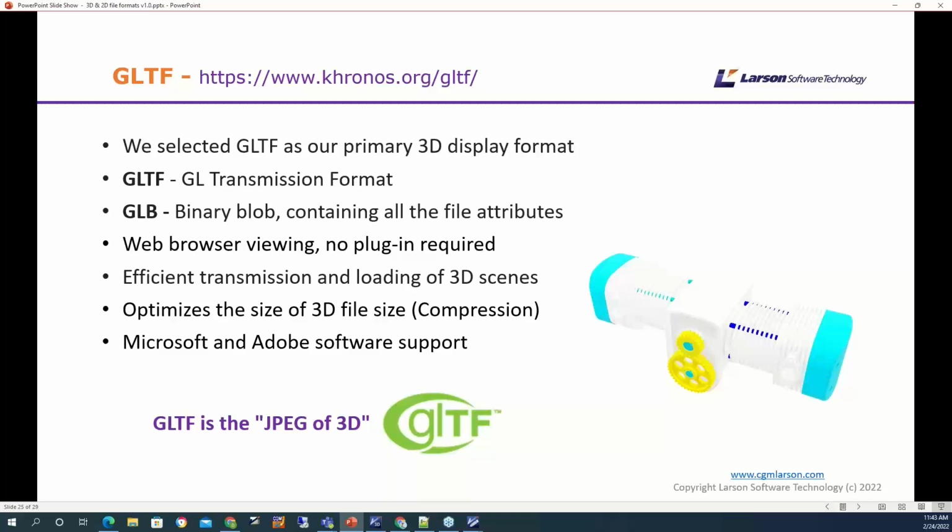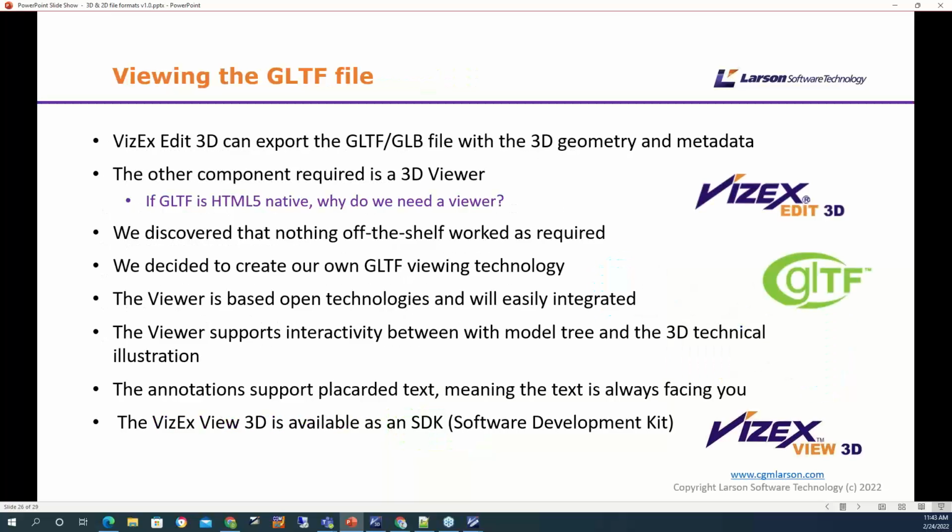So that should give us really good interoperability with other software. We can export as a GLTF, or GLB, it's the same file but a binary file. GLTF tends to be a bit larger, but GLB is a much lighter format, and it's one we favor.